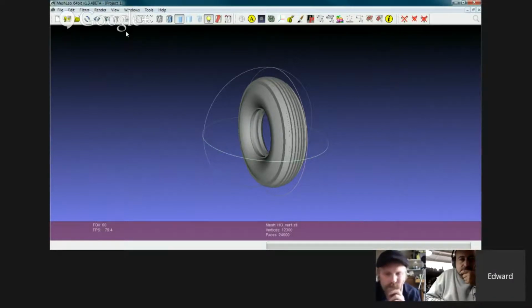So that, you know, if I take 360 degrees and I divide it by 20, that's 18 degrees. 20 degrees gives you 18 sections, which means you would have to do a 20-degree section of that tire and then put your lug on that to fit so that when you spin it, you add section to section to section, that the lugs would line up correctly. That's what I'm trying to say.